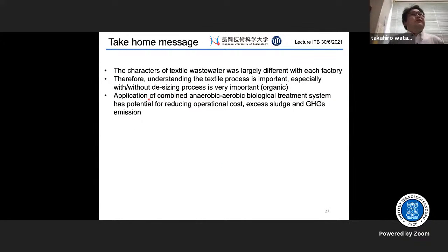So this is the take-home message from my lecture. The characteristics of textile wastewater are largely different in each company, each factory. Therefore, understanding the textile process is very important, especially with or without a desizing process, because whether the wastewater contains easily degradable organics or not is very important for the biological system. And application of the combined anaerobic-aerobic biological treatment system has great potential for reducing operational cost, excess sludge and greenhouse gas emissions.